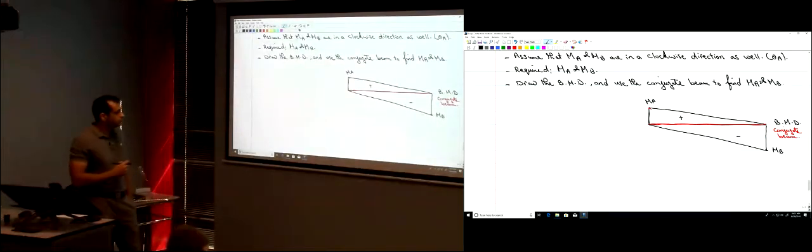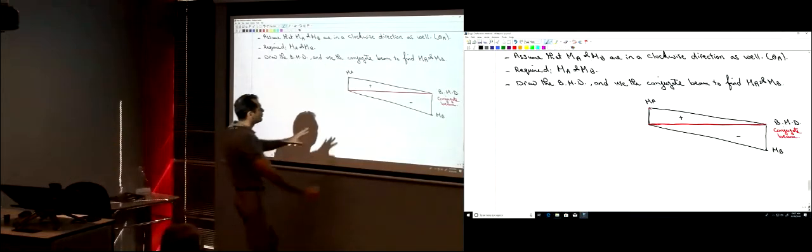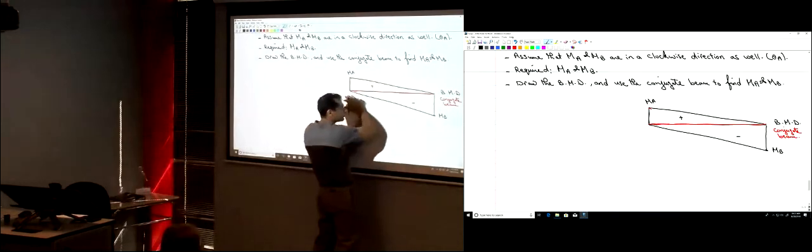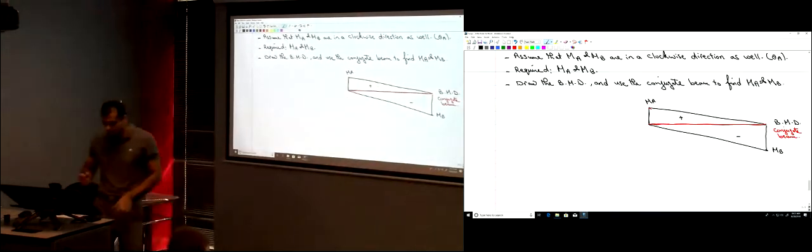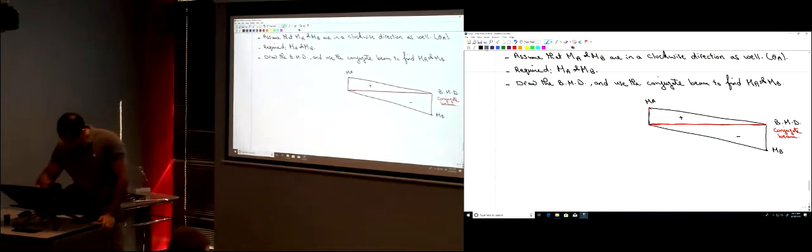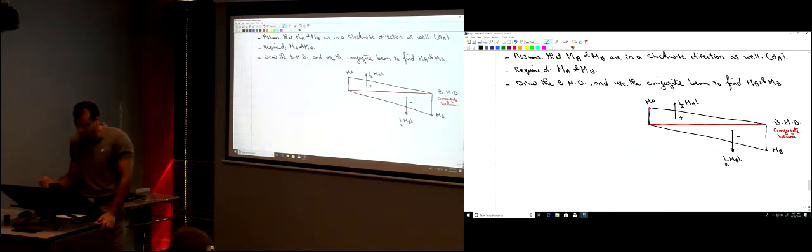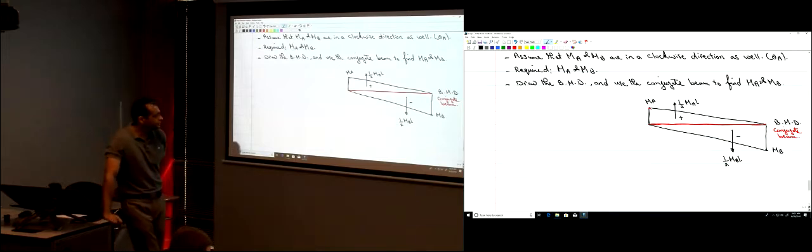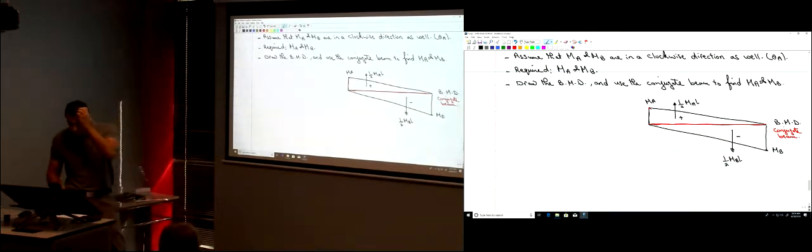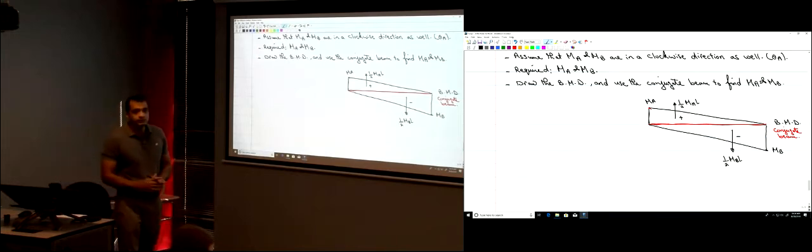So now, I'm going to do an easy step. Just find the equivalent force to this triangular load and the equivalent force of this triangular load. Okay? So how much is this force? It's going up. It's triangular, so it's 1/2 MA times L. This one going down, it's 1/2 the base times the height. So 1/2 MB times L. Those are the two forces, right? And now this is the conjugate beam. Do you agree that this is the conjugate beam?